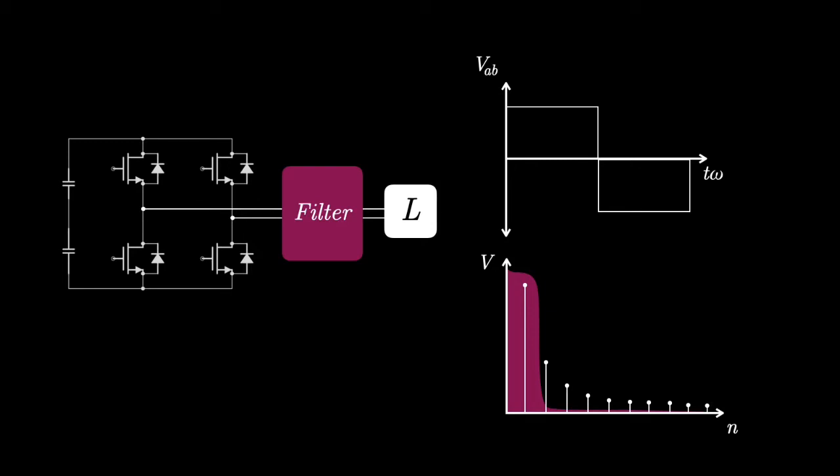The design of such filters tends to be challenging when the third and fifth harmonics close to the fundamental are high. In most cases, effective filters require large size and a high number of capacitive and inductive components, resulting in bulkiness.